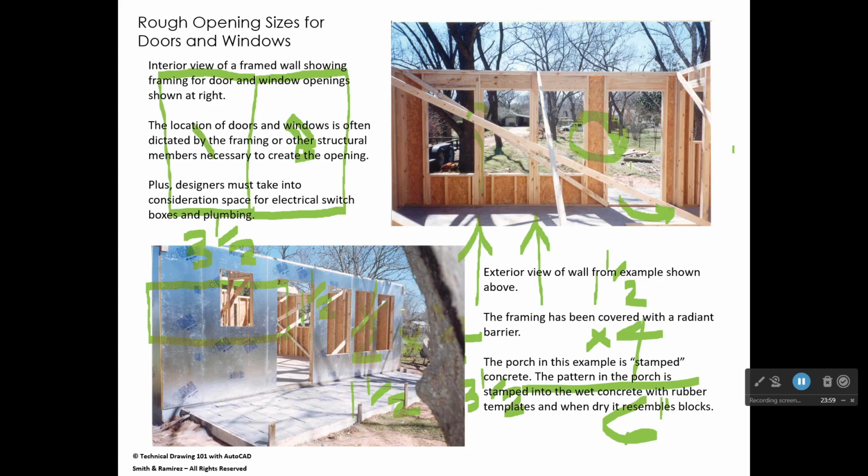So if you got that swing wrong and it swung into the room this way, so when you walk up, the handle's on the left-hand side, or the right-hand side rather, no, it would be the left. You would actually, by swinging the door open, put your light switches behind the door. That would just be another little weird design thing that you've got to avoid.